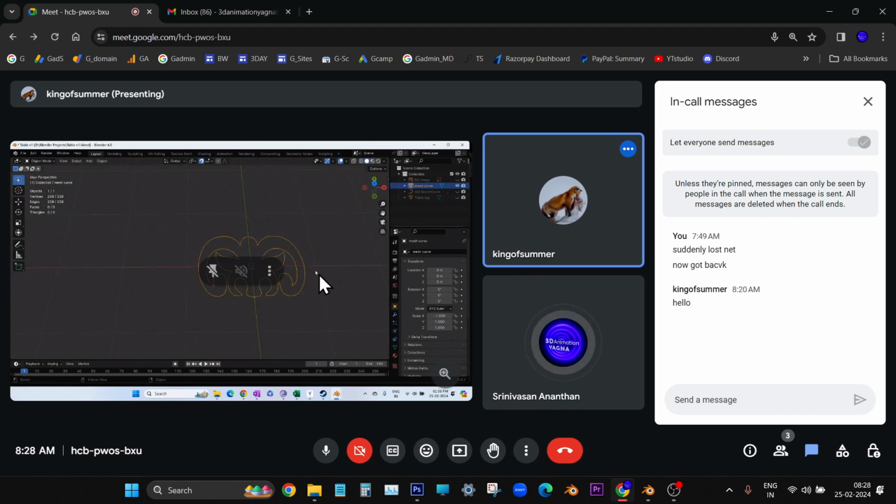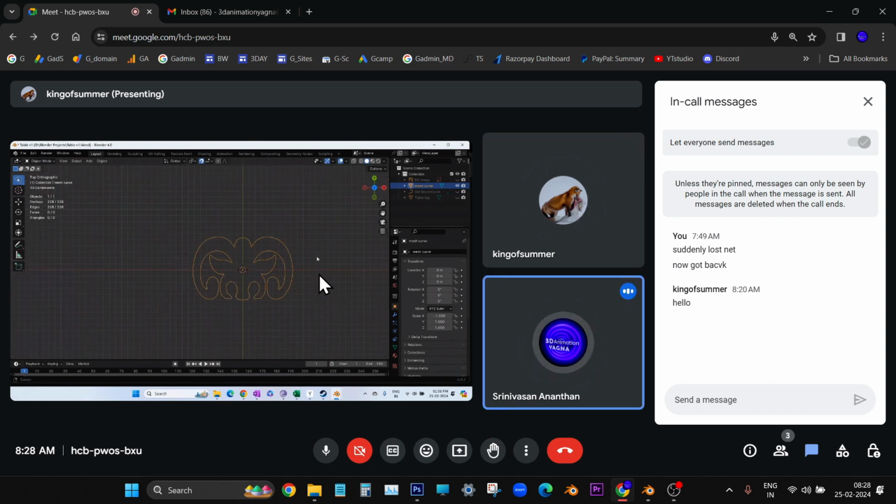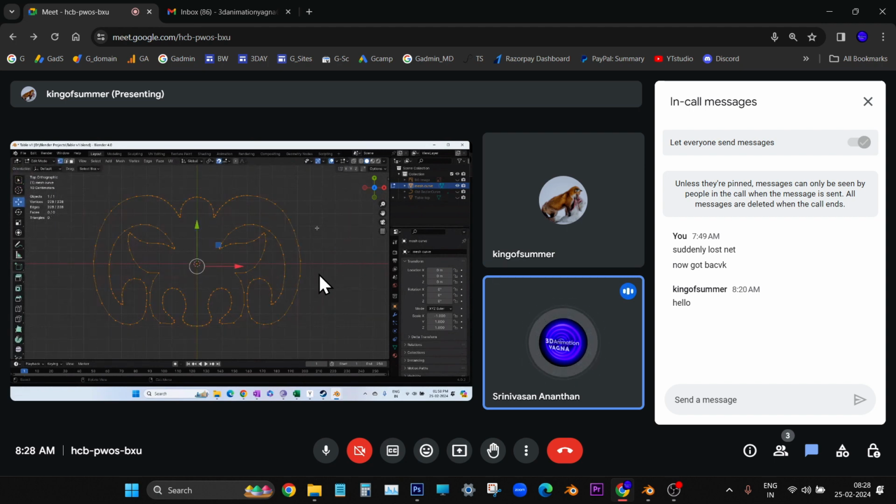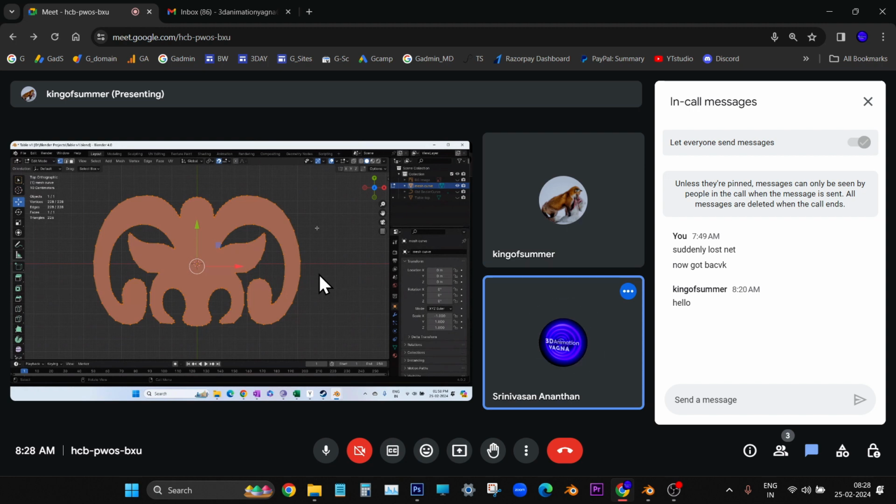Yeah. In the top view only we are going to do everything, so no need to change from top view. Now zoom in. Now go to edit mode. Now we have the equal number of vertices on the left side and right side. Very good. Nice. Now you made it a face also. You are in vertex mode, that is also okay. You can switch off this horseshoe magnet snap icon. Right.